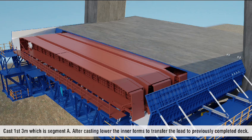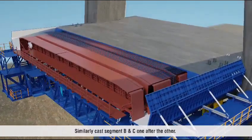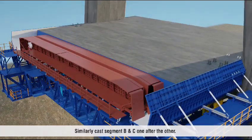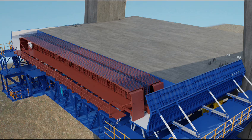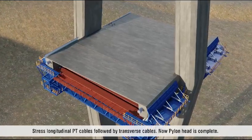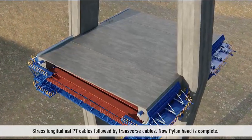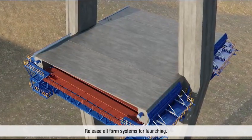After casting, lower the inner forms to transfer the load to previously completed deck. Install temporary casting hanger. Similarly, cast segment B and C one after the other. Stress longitudinal PT cables followed by transverse cables. Now pylon head is complete. Release all form systems for launching.